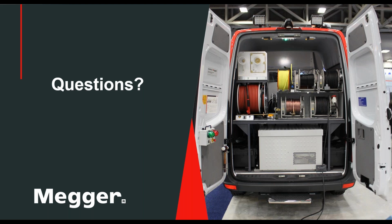So anytime you send high voltage out, you must observe that protocol, because otherwise you might be sending high voltage to... take a good example: on a low voltage circuit, if you have a meter box connected and you would fault locate and you send 1,000 volts down that cable, you would blow everything up in that house, right? So you must be isolated. The moment you use high voltage, you must use isolation on the far end, and on the front end it's also isolated because you're connecting your equipment to it.